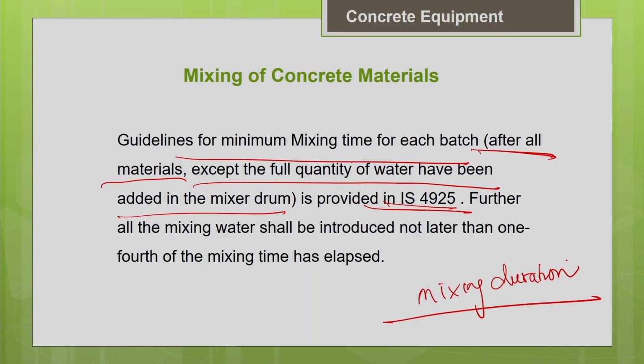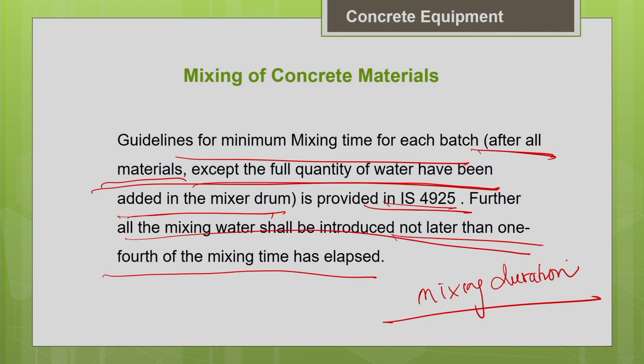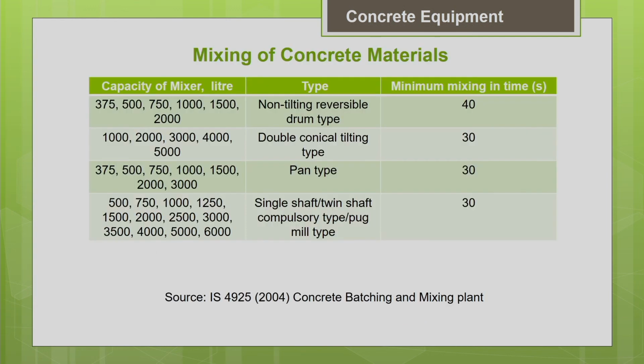So, after all the materials are added except the full quantity of water, your mixing time is taken into account. Another important thing you have to note here is that all the mixing water should be introduced not later than 1/4 of the mixing time has elapsed. That means, though you add the water in stages, the entire mixing water should be added before 1/4 of the mixing time has elapsed. This is the guideline available in IS 4925. We are supposed to follow the guidelines. So, this is what I told you.